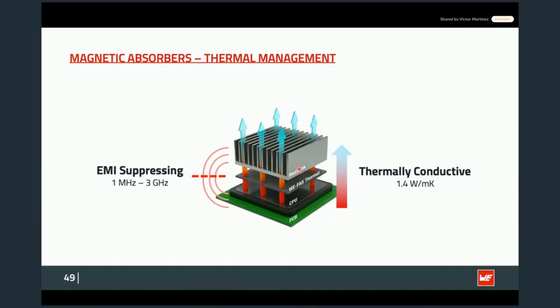So you have over here a metallic surface, a blank space, or air, and then here you have another metallic surface. So you have over there a capacitor. And then that capacitor can create some unexpected problems that maybe you didn't think about in advance. And then probably the first way to act will be, okay, maybe I can remove the heatsink. And then your colleague from mechanical engineering will reach out to you and say, don't do it. The whole thing will just melt. So then the heatsink is a must.